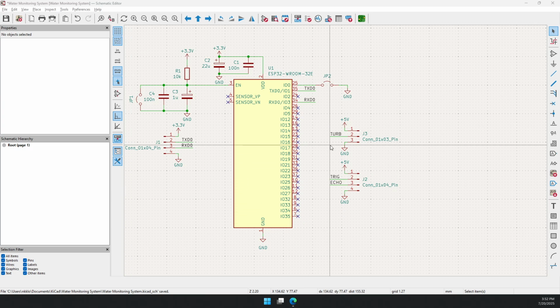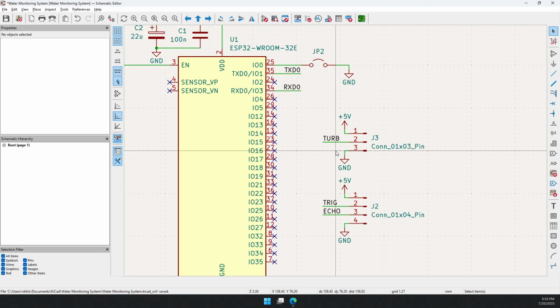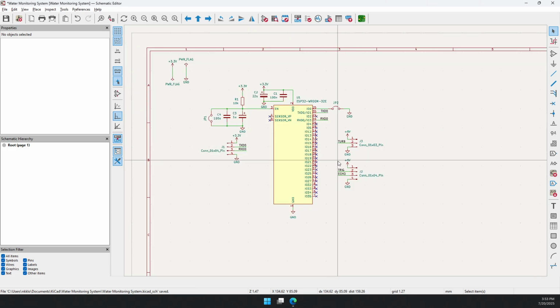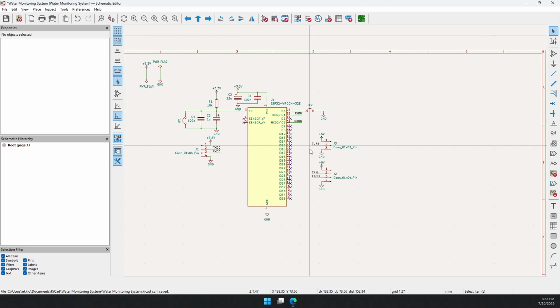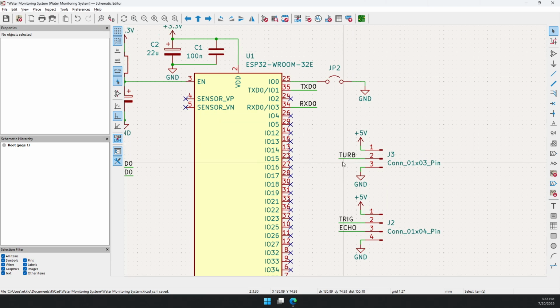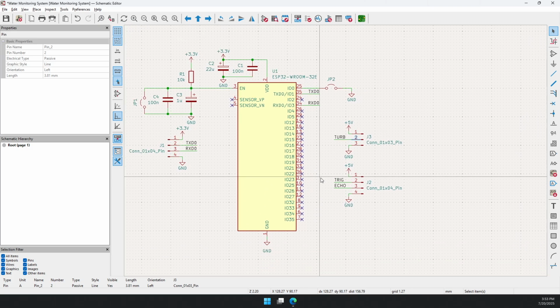So you said if we were to leave the error there, the symbol not connected error, and we went on to PCB design, will we be able to route? Short answer, I think, is no, though I've not tried that, because on your schematic, this pin 2 is connected nowhere to the ESP32.